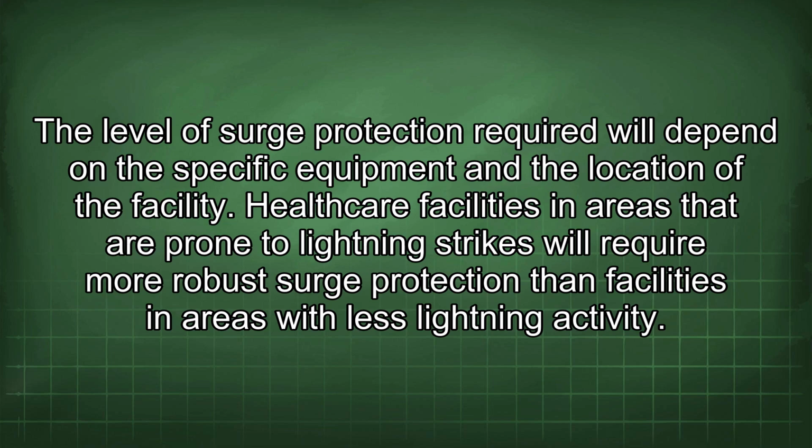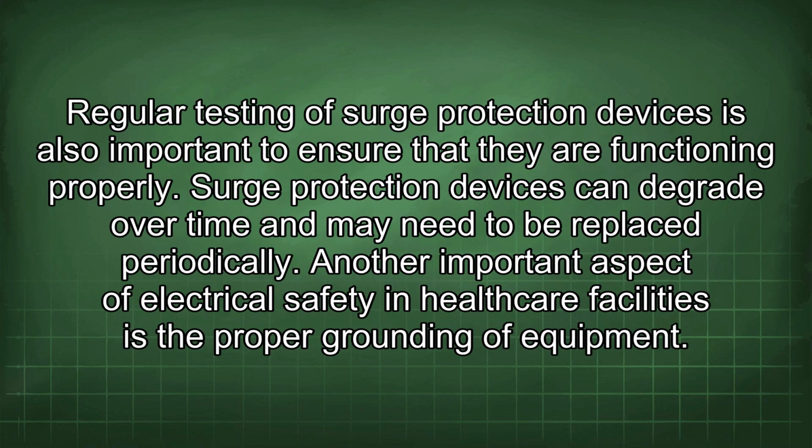Healthcare facilities in areas that are prone to lightning strikes will require more robust surge protection than facilities in areas with less lightning activity. Regular testing of surge protection devices is also important to ensure that they are functioning properly. Surge protection devices can degrade over time and may need to be replaced periodically.